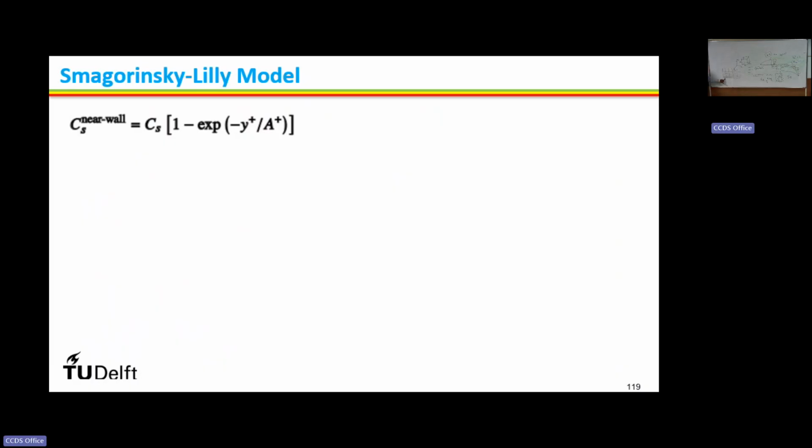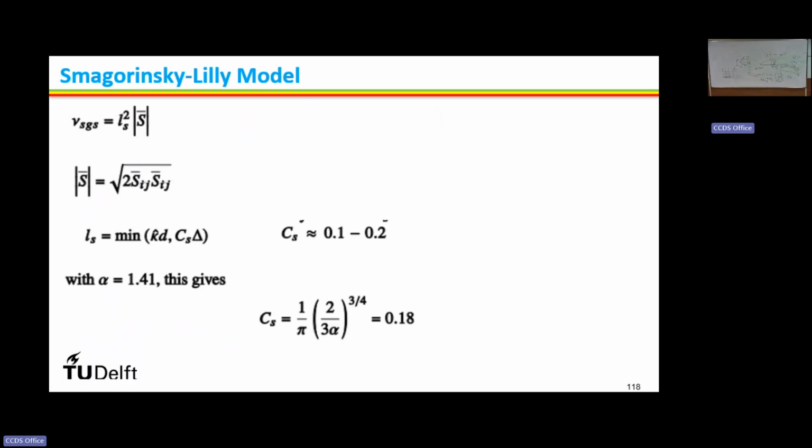Close to the wall, the turbulence should what? Damp away. The wall is a damper; it damps away the fluctuating turbulence. In the original formulation of Smagorinsky and Lilly, they don't account for the wall effect, meaning the presence of a solid wall, where the turbulence will damp away. So finally there is a method, the CS, that we are calculating the coefficient over here, right?